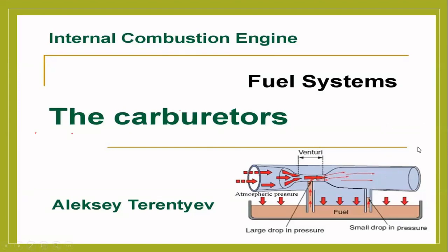Energy can't be destroyed, meaning both energies are constant. Adding up both energies, pressure energy plus kinetic energy at one end is equal to kinetic plus pressure at the other end. We will take these two ends, the middle and the start. Here the orifice is big, and you know when the orifice is big, velocity is low. How is that possible? What equation do we use to prove this?